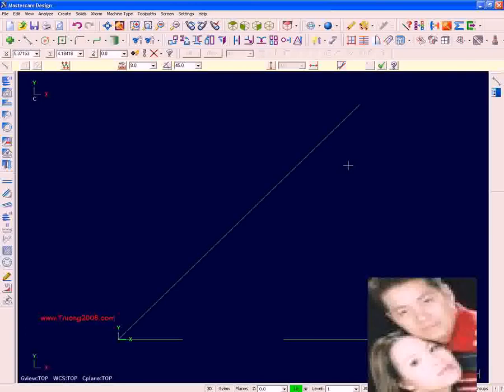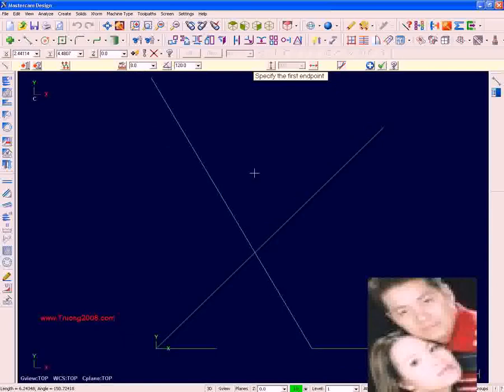To illustrate the flexibility of Mastercam X, I'll create the 120-degree line by sketching its start and end point and then entering the proper length and angle. So I'll go ahead and select this end point here and stretch it somewhere out on the screen and click. I'll select 8 inches from the drop down in the function ribbon bar. Notice how your inputs are remembered. I'll then type 120 degrees and hit enter. My live entity display updated. It looks good, so we can apply.